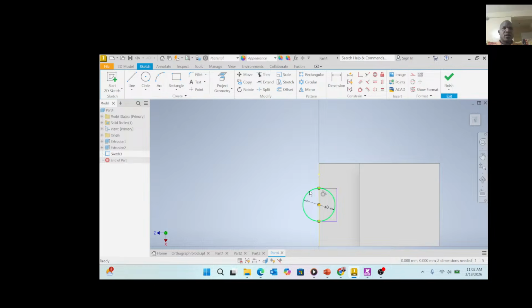And I will now delete the circle. It was just a guideline. It's given me this length, from the center of this part to this part, at a diameter of 40, which means from the center to here is 20, and the interior is 20 millimeters. Before I dimension it, I'll do that later, but for now, I have finished drawing.